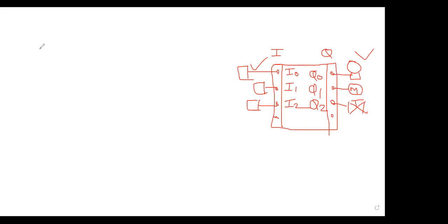Let me draw this. Let me make a ladder diagram. Program, final coding I'm making. As we have to get the lamp on, I shall use an O, and here is Q0. And this is your final program. Nothing else to write down, no printf, scanf, nothing, no if and else. So this is the program for this simple example. Now, after making this program, I need to send it to the PLC. And then when I go to the machine and press this switch, this lamp will be on.